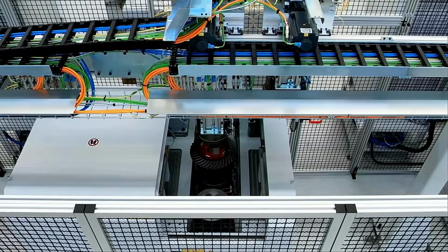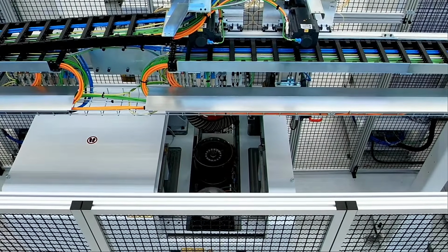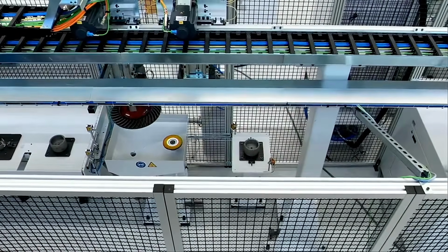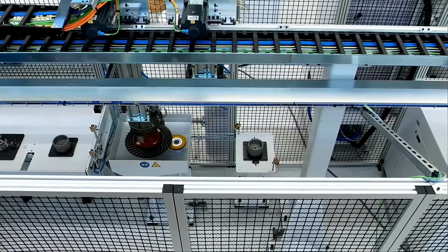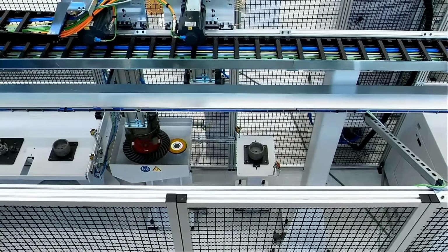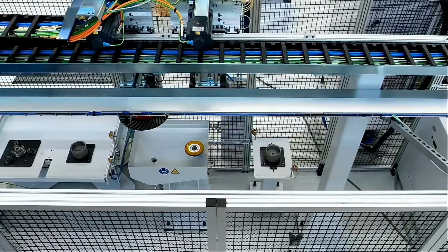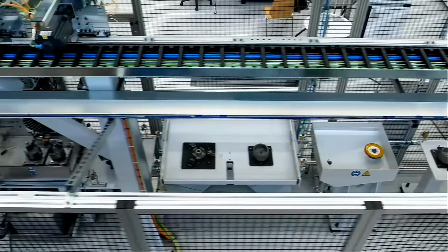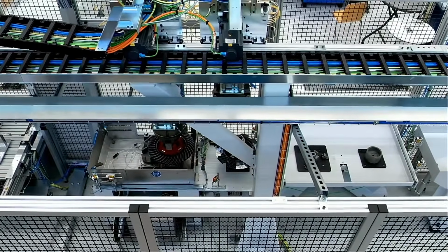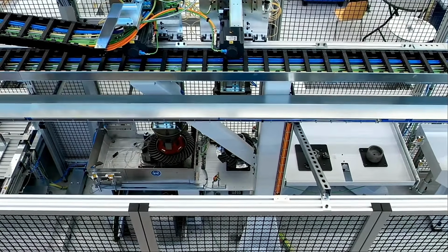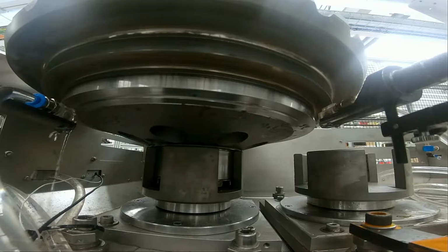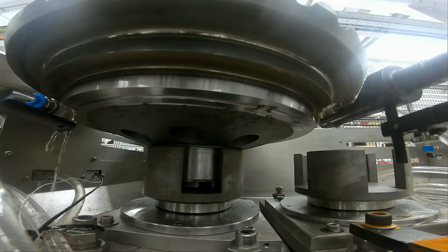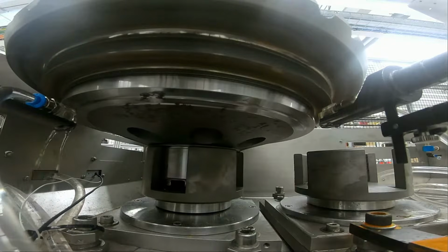After we have welded the components, we move the part, as I mentioned, to the brushing station. This brushing station is responsible for brushing both weld seams, again to make sure that there are no spatters on the welded surface. The final and very important process is now to check the quality of the weld seam. Here we have an implemented ultrasonic testing station. Software as well as hardware is developed by EMAG, so we are able to integrate our own systems.